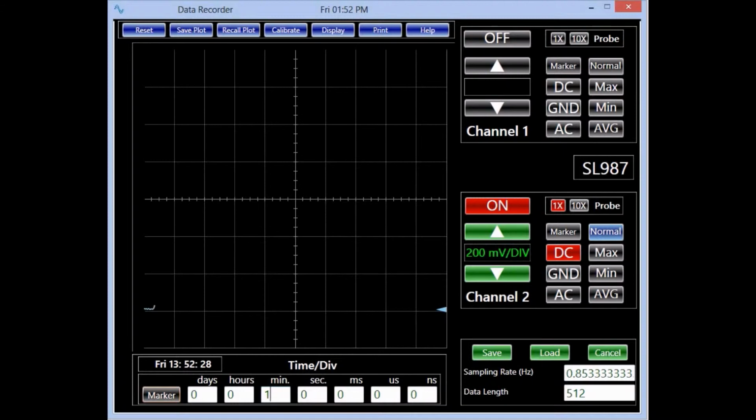The light bulb would be turned on and off every few minutes. Therefore, the timing scale would be set at 1 minute per division. To have a good viewing range, the vertical scale of channel 2 is set such that every division would correspond to 5 degrees Fahrenheit. In addition, the DC position of channel 2 is adjusted to make the negative 600 millivolt DC level translate to about room temperature.